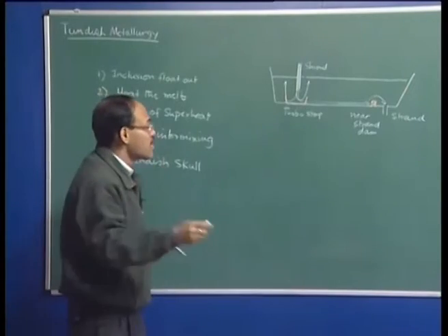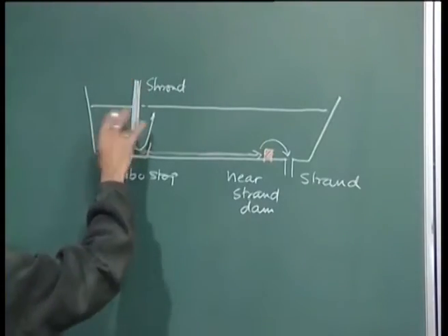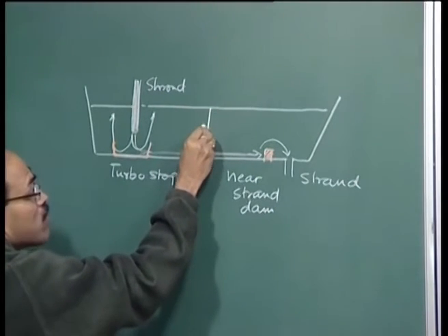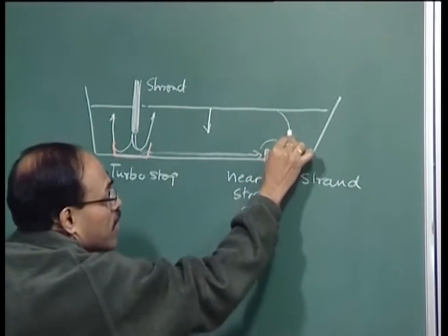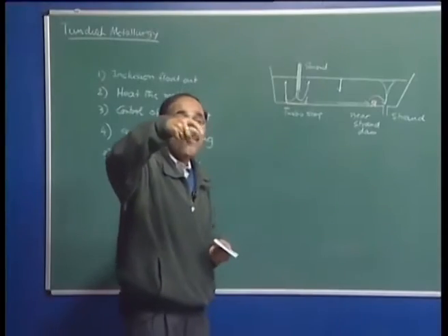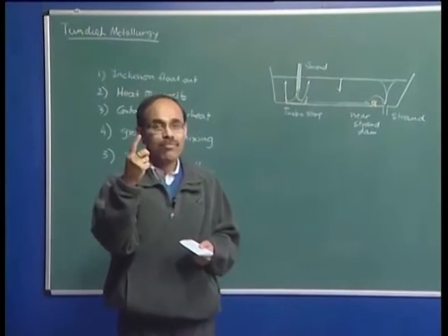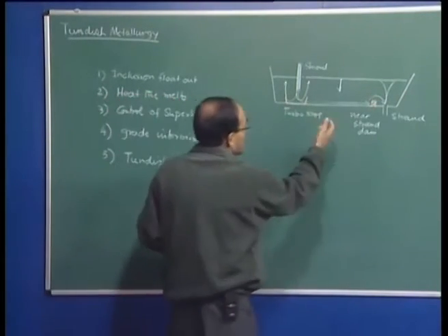So, imagine the last heat and you have metal in the tundish, and nothing is coming into the ladle, because that has to be the last heat. Then the interface goes down, and at some point slag vortexing is going to start, just like when you open a tap in a sink, you must have seen that funnel vortex form.